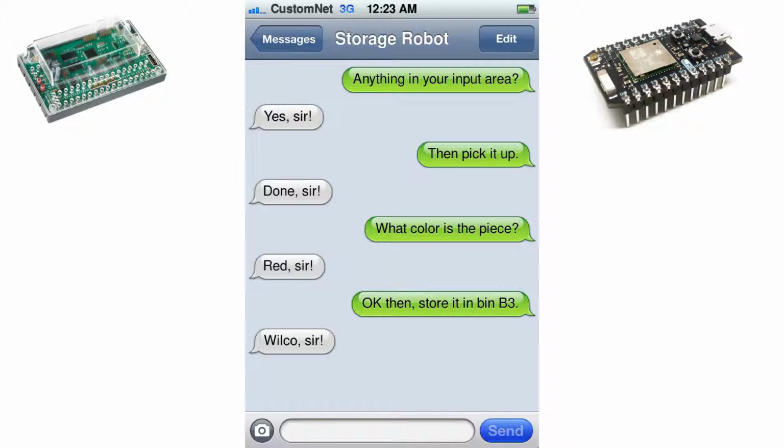The Photon asks, "Do you have a piece in your input area?" To which the robot responds with, "Yes, I do." The Photon then tells the robot to pick up the piece, and after that has been done, tells it to identify its color. After it learns that the new piece is red, it tells the robot to store it in a certain location. This is an example of a so-called master-slave communication.